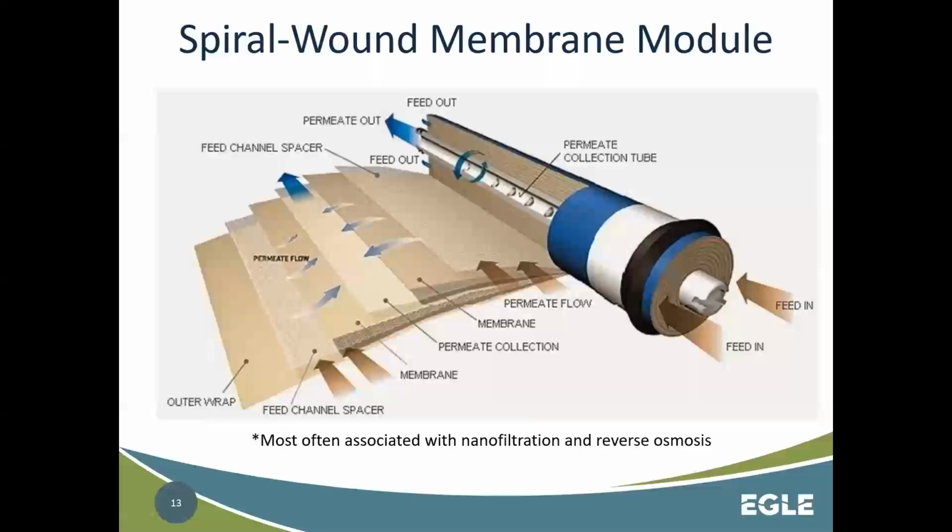Okay. I mentioned we are not going to focus a whole lot on nanofiltration or RO, reverse osmosis, but this is what that type of membrane looks like. And again, this application would be more for something special like nitrate removal, PFAS removal. Sometimes you'll see it for softening. And so it's so small, it can remove your hardness